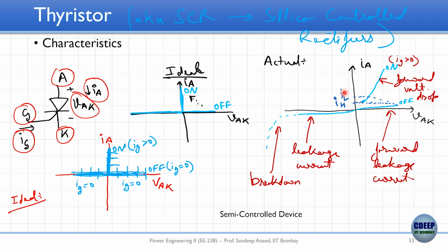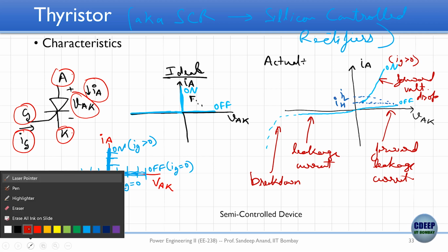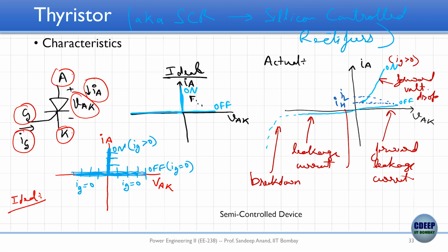This is a semiconductor device, there is no physical arc happening anywhere in this. But just to correlate with the previous example, you need some amount of latching current for the device to turn on and some amount of minimum holding current for the device to remain on. So these are the two terms which are a bit new. And even if you don't remember them, that's perfectly fine.